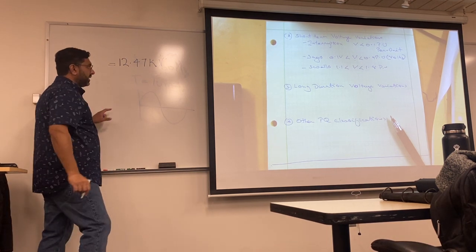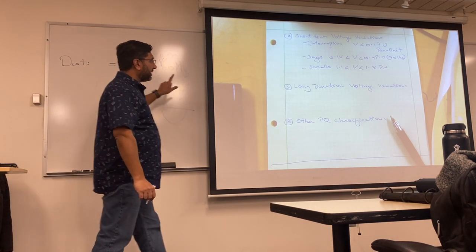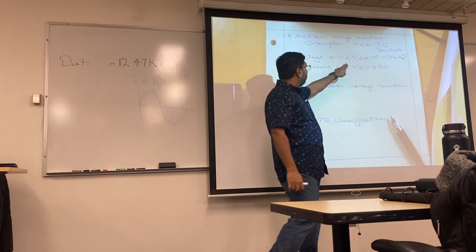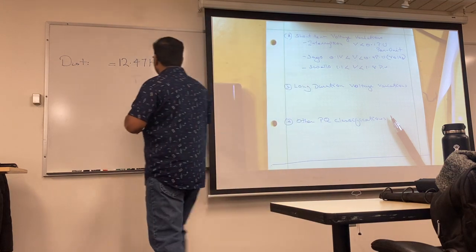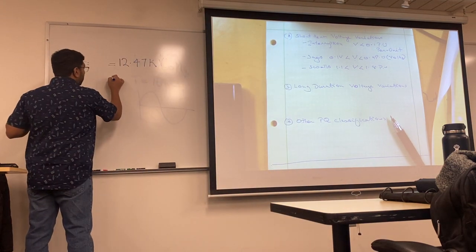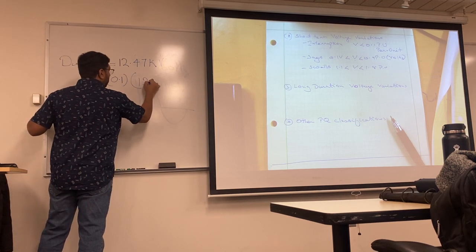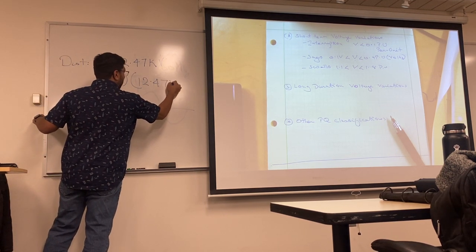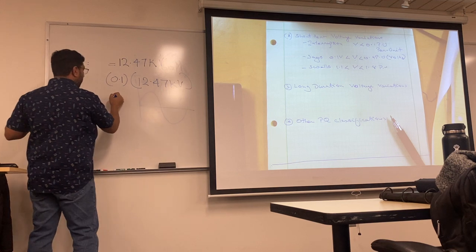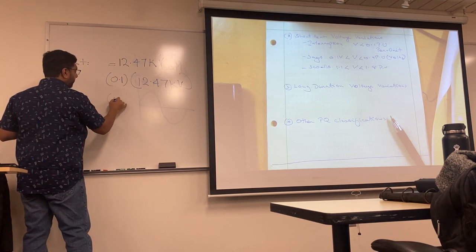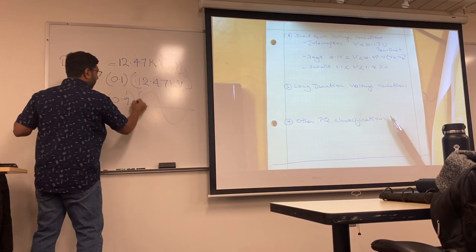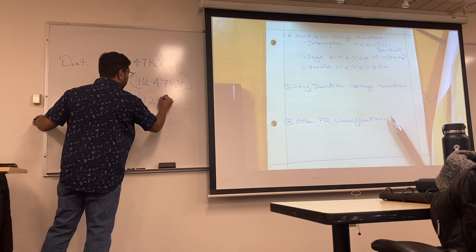What this is telling me is a sag happens when my voltage is between 0.1 and 0.9 of 12.47 kV.